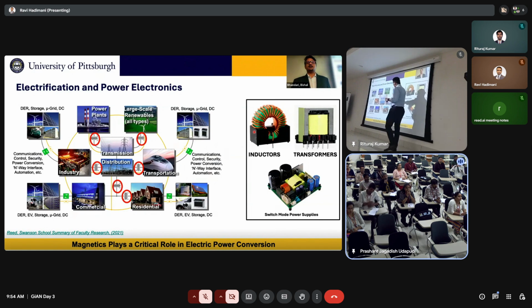So the transformers are nothing but electrical steels. You take the regular steel, add some silicon, and you get what is called silicon steel or electrical steel. So these steels also, you remember the soft ferromagnet and the hard ferromagnet. These are soft ferromagnets. They don't have any coercivity. Well, they have very little.